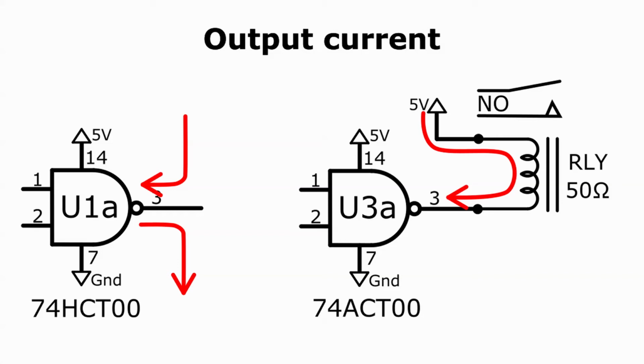If you are just learning about coils, you'll already know that one of the important properties of a coil is its inductance. When the voltage applied over a coil changes with time, the inductance is the key measure of how the current will change. But in our case here, the applied voltage is a constant. The current flowing through the coil will also be a constant, or at least it will be constant after a very short period of time during which the inductive effects take place. This 50 ohm resistance is the resistance of the copper wire used to wind the coil. The wire will resist the flow of DC current in the same way as a normal resistor.